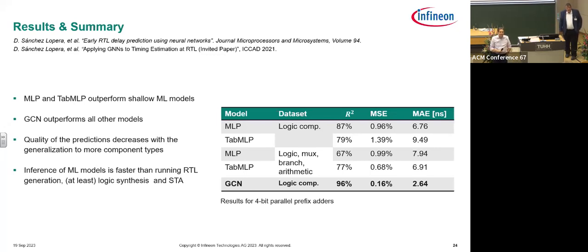My question is specifically about one of the slides where you talked about that we cannot trust the black box optimizations. If we have any sort of wider optimization like an ILP, should we limit on the IP modules design itself, which would be more like a high level SoC design and not going within the routing and the STA part of things? Over there might be huge search spaces, but we have surrogate models like cycle accurate simulators, which can actually help us guide the search space effectively, that, okay, design choice A versus choice B.